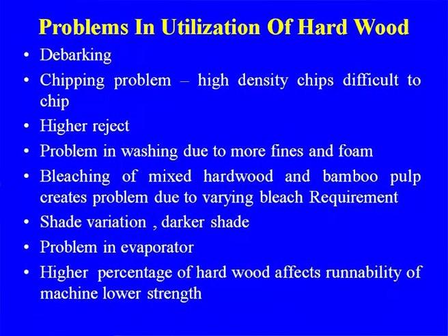Bleaching of mixed hardwood has varying bleach requirement, shade variation, and some problems in the evaporator. A higher percentage of hardwood also affects the runnability of the machine. So, we are not operating 100% hardwood except eucalyptus, because eucalyptus has better quality than other hardwood species.